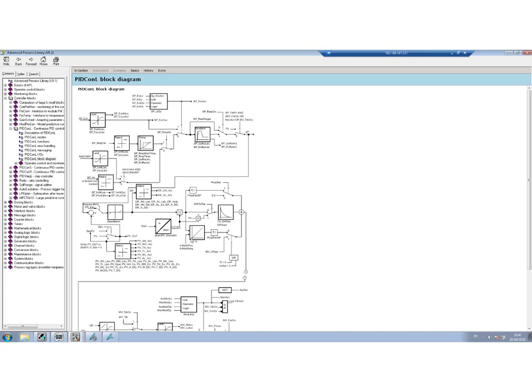Here you have the integral action. Well, you see here the integrator, and as you can see here, you can switch between what comes out of the integrator and a bias that you can choose. So this is the bias from the course, this MV offset, and depending on if you have TI equal to 0 or that you choose not to have integral action by setting this Boolean parameter here to 0, you will switch between the output of the integrator and the offset, and what comes out here is MV.